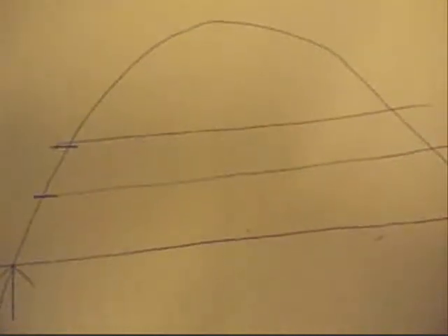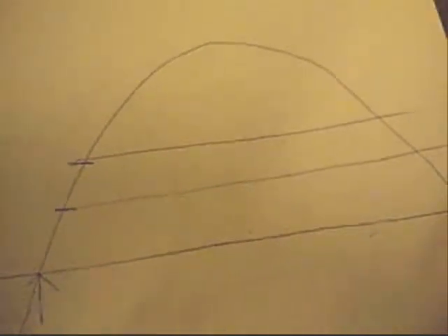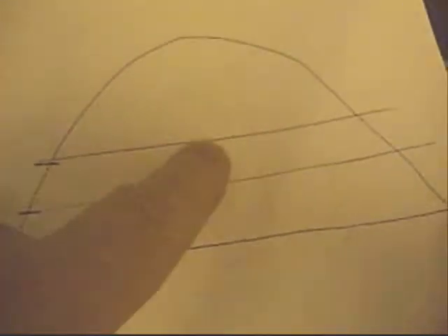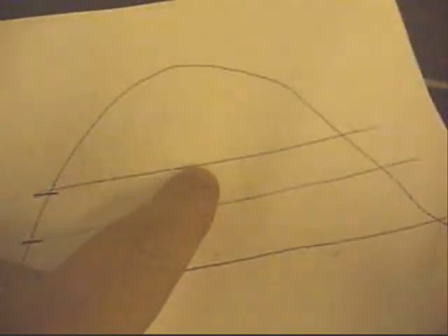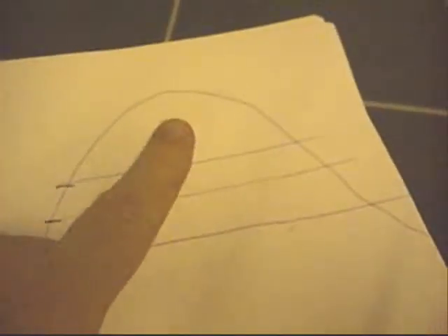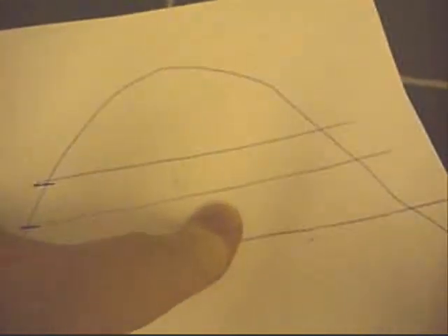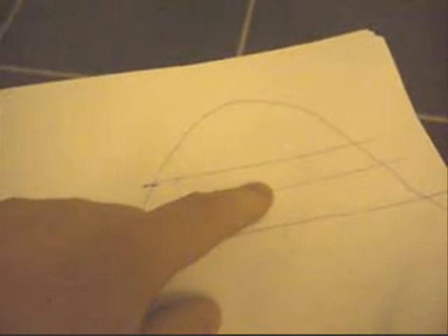There we go. As you can see, those two lines indicate minimum trigger voltage and the saturation voltage. That's the voltages without the pot in place, so if you just connected the trigger coil straight to the transistor. With the pot, obviously you move this lot further up.